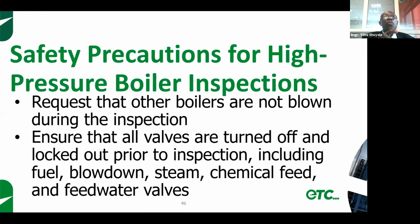Now, request for other boilers to be shut down, especially if you have so many boilers in series, you will have to ensure that other boilers are not blown. That is bottom blowing of the boiler during your inspection, because the noise from blow down can cause a distraction for the guy who is inspecting the boiler. Okay.